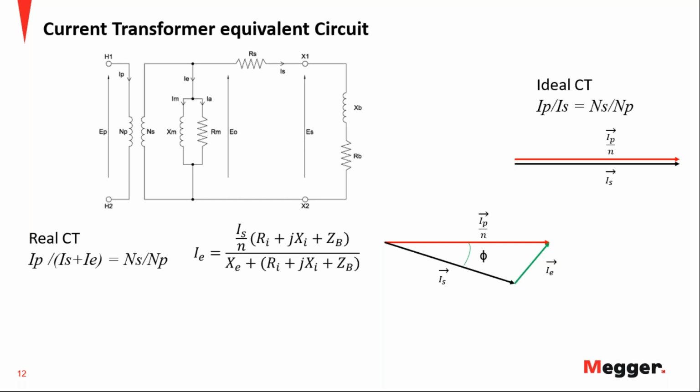So if you think about the ratio correction factor having a minimum or a maximum, and you think about the power factor limits defined by the class, that means that you are going to have a magnitude that is going to be less or higher than what the proportional primary current is. So that's where you get your maximum and minimum ratio correction factor.